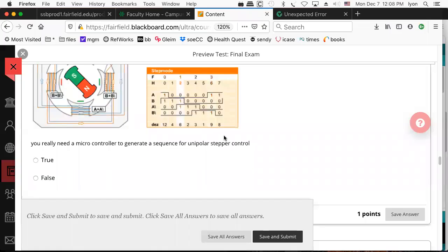And that's going to give you the ability to control the stepper motor if you can create a clock for your finite state machine. You could use a 555 timer for that with a little diddle pot, and then you could choose how quickly the stepper motor turns. Because if you ran at full speed, it would run at several megahertz, and motors don't step at several megahertz, at least not the ones that we have.